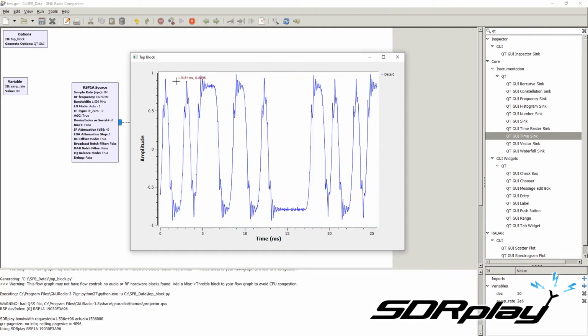Let's stop when some data is shown, and you can see that it's a signal that goes from around -1 to around 1, but there is a lot of noise. You see that it is not a square wave. There is a lot of noise when the transition happens, and when it is a high value and a low value, you see that it oscillates a lot. But already we can see, for example, this is a 1, this is a 0, 0, this is a 1, a 0, this is probably 3 or 4 ones. So we are in the right direction. We need to remove a little bit of noise.